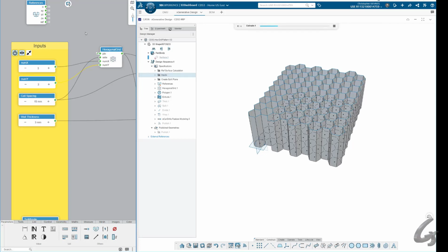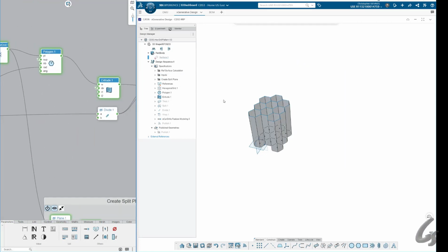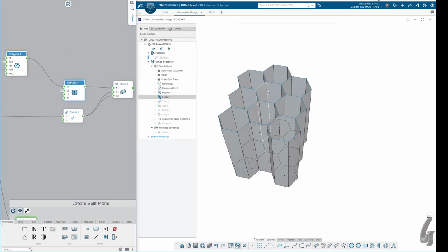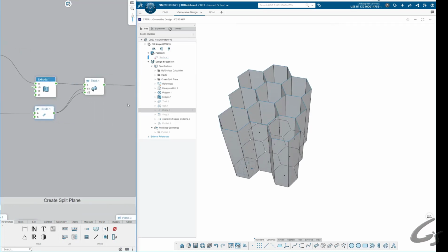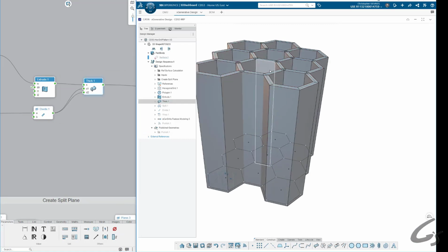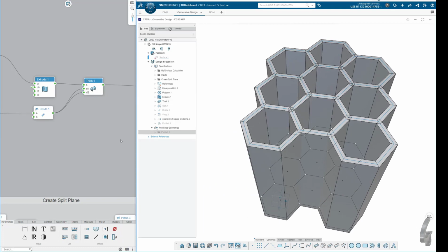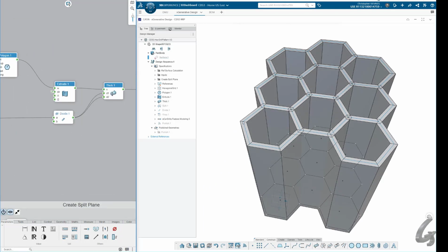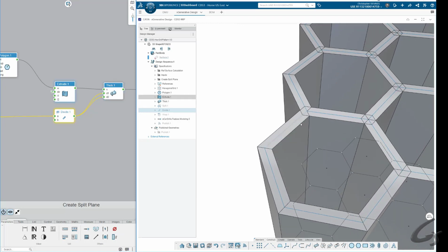Now, as we start to build out the geometry to do this, we need to turn these surfaces into real physical volumes. So, we can thicken the surfaces that I've created, and I'm feeding it another parameter of wall thickness. And by dividing that wall thickness in two and feeding it into each direction of thickening of that surface, I'm able to center my volume on that surface.